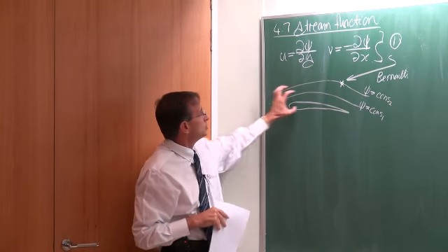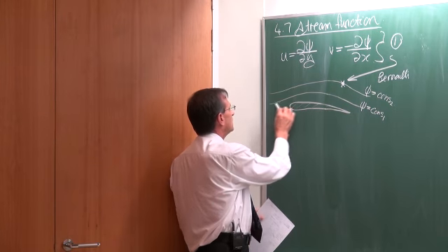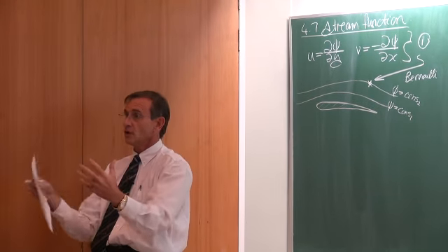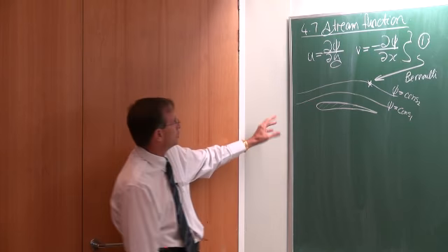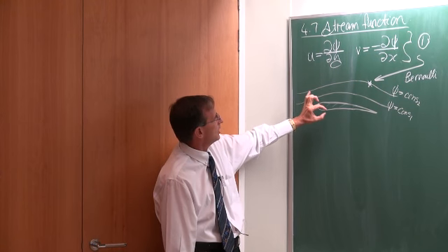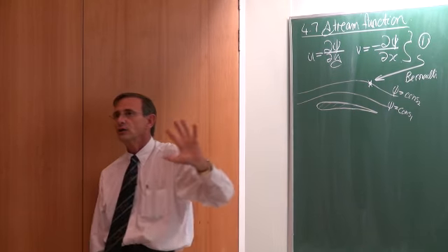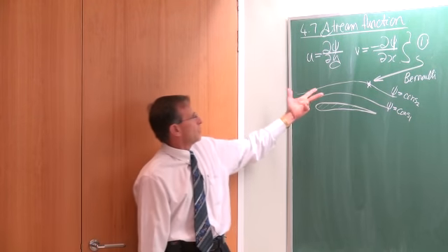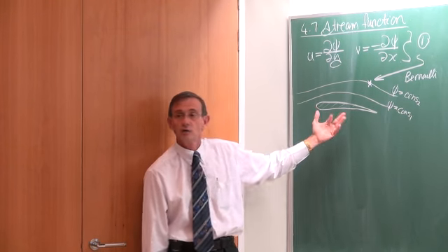So the result of that is that if you can imagine a flow particle around a body, for example, an aeroplane wing, and if you can get all the streamlines, just by looking at it, you can already understand what will happen with the flow. Although my drawing is not very good here, typically the streamlines here will be very close to each other, while here the openings would be much more open. Just by looking at that, you can immediately see where the areas with the high velocities and the low velocities are. Where the high velocities are, there will also be low pressures from the Bernoulli equation. The low velocities would be the high pressures.